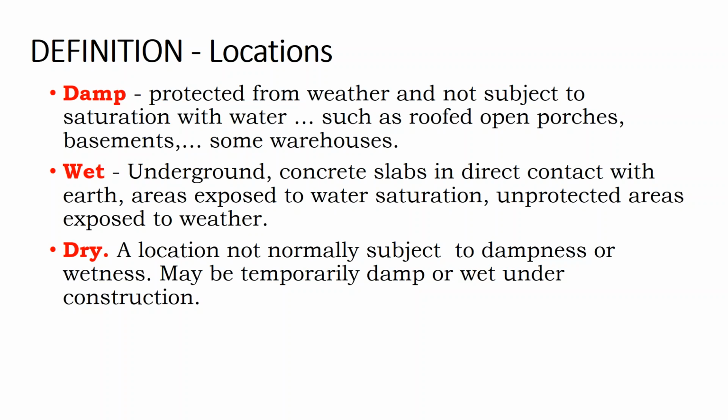And there are some advantages of direct burial cabling as opposed to putting wire in conduit. Such as temperature: you might have a cooler cable in a direct burial run than if you entrap it in a conduit. Conduit does provide physical protection. I'm not saying to not use conduit, but it doesn't have all the advantages that you think it has in terms of being able to just put in wire and re-pull wire. Conduit can break, and then it becomes a wet environment.